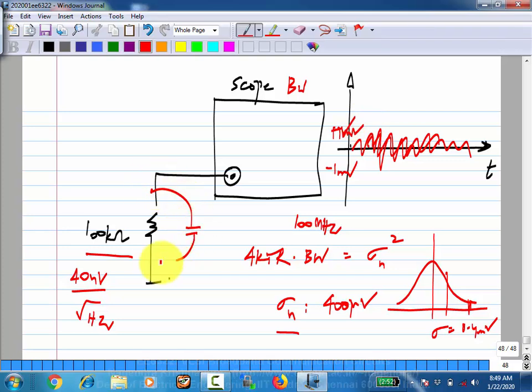And I assume that this 100 kilo ohm resistor has no parasitic capacitance and it goes to the oscilloscope. The oscilloscope reads the value across the 100 kilo ohm resistor but with its own bandwidth limitation. But if I had, let's say, a 1 picofarad capacitor across this, what would happen? What would you see? The bandwidth would be limited by this one. If it is not limited by this one, it will be limited by the oscilloscope bandwidth. So you have to also see where it gets limited. In this case, 100 kilo ohms times 1 picofarad, what is the bandwidth associated with this?